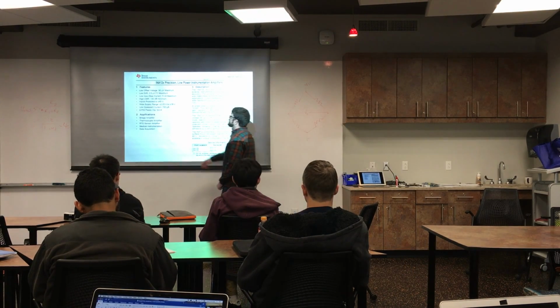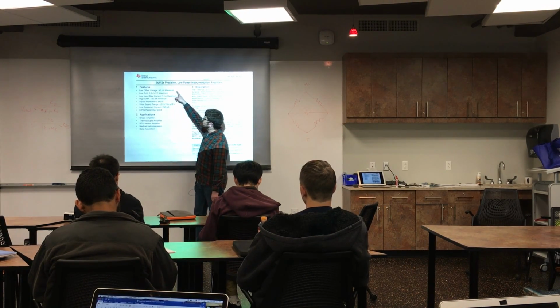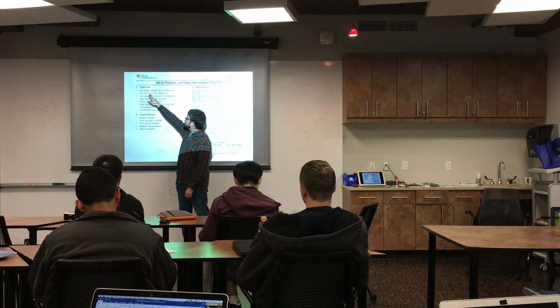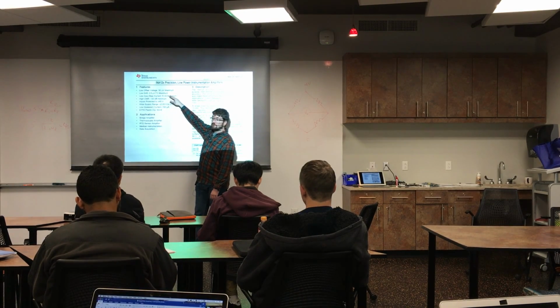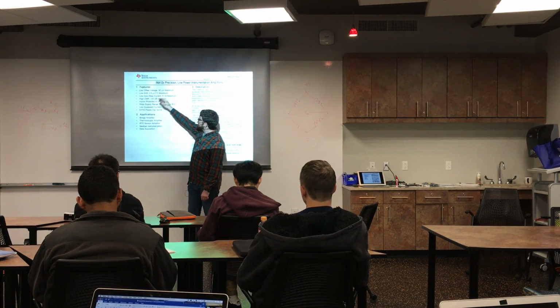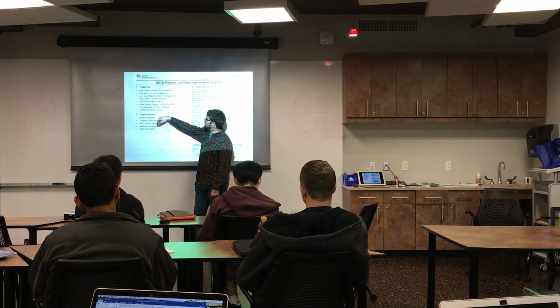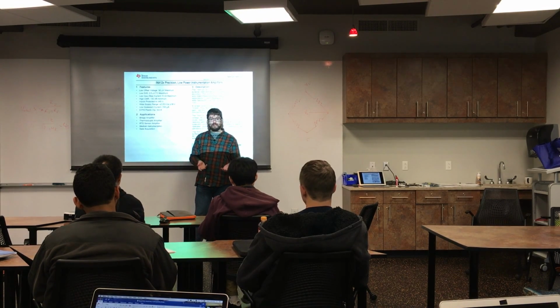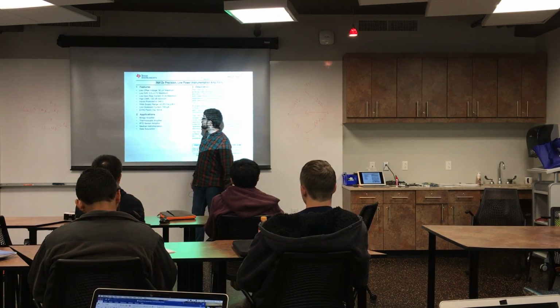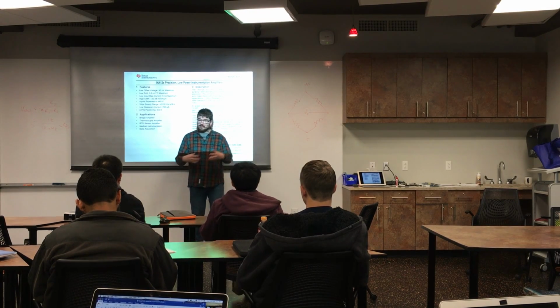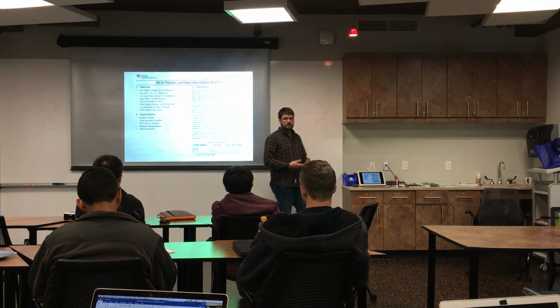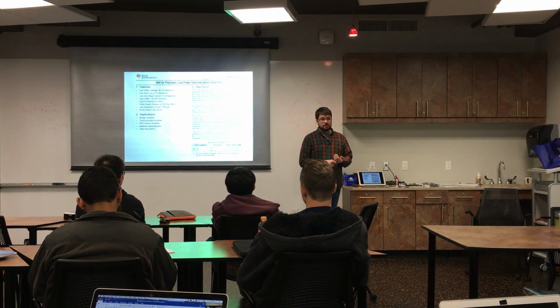But yeah, so look at the offset voltage is 50 microvolts maximum, 0.5 microvolts per degree drift maximum, 120 dB common mode noise rejection. So remember, 40 dB would be like a factor of 100, so we're way, way above that. And a lot of instrumentation amplifiers have these built-in things like overvoltage protection.